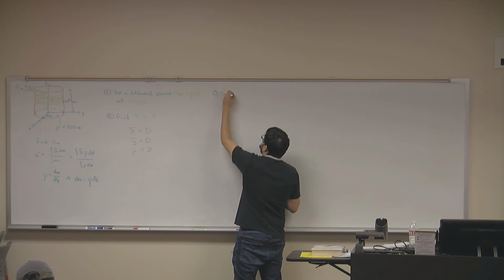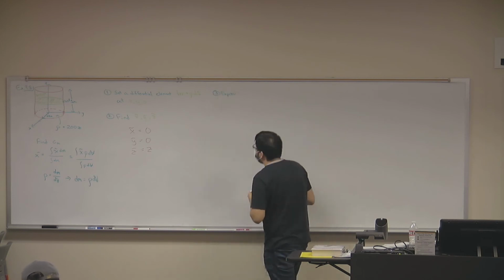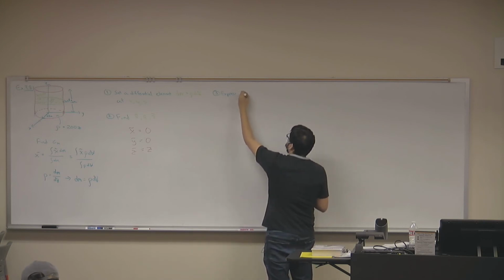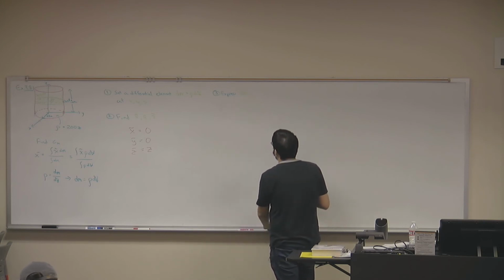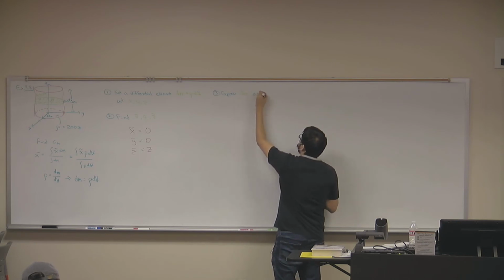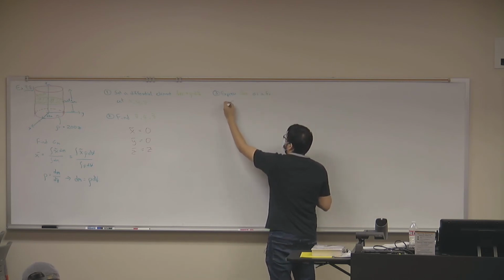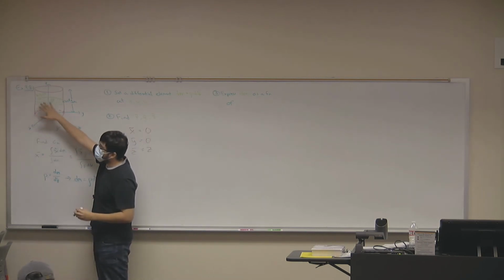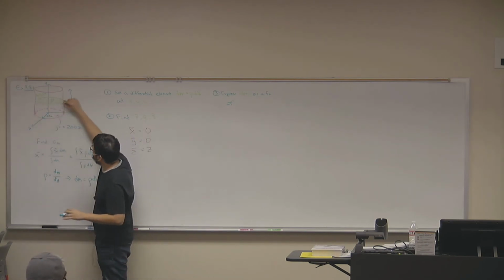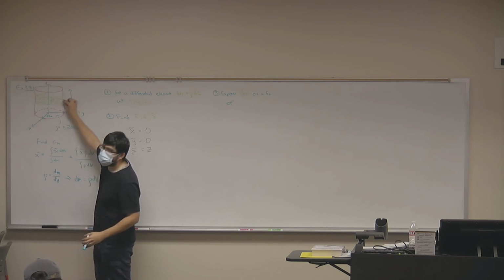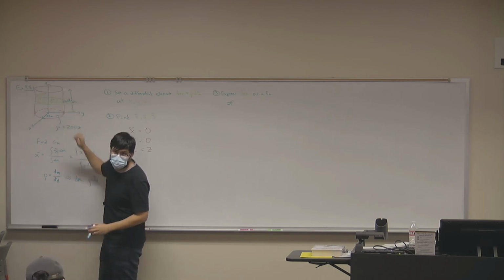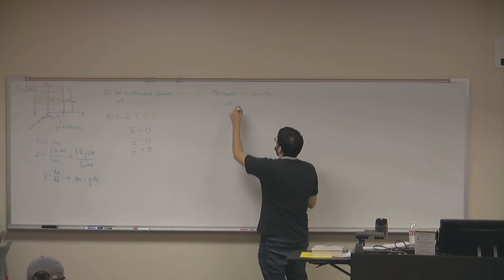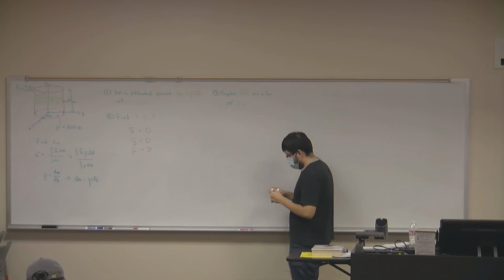So we want to express our differential element's mass. So we're going to express dm as a function of what? You have your differential element. Notice that for your differential element, we have two finite dimensions and one infinitely small dimension. What's that one infinitely small dimension? dz, right? Okay. So we want to express our differential mass dm as a function of dz.